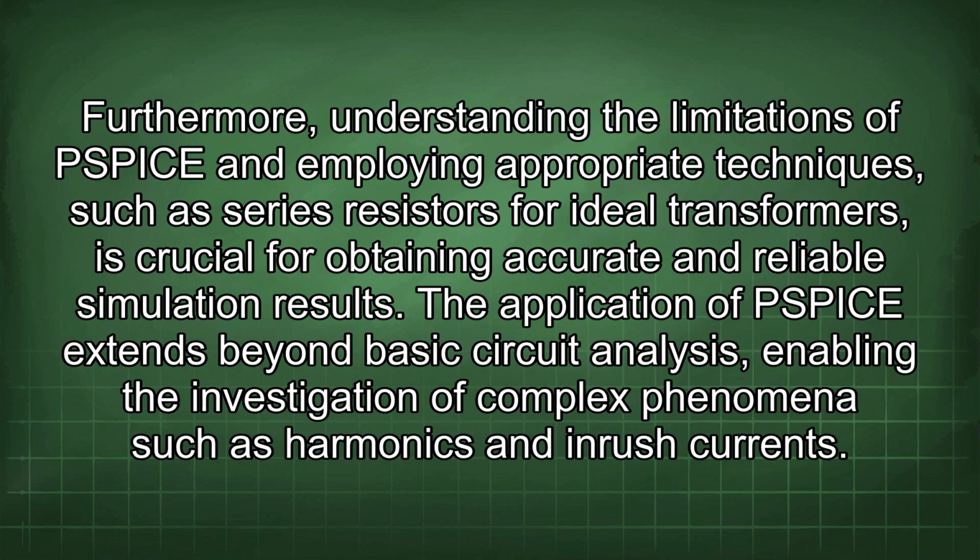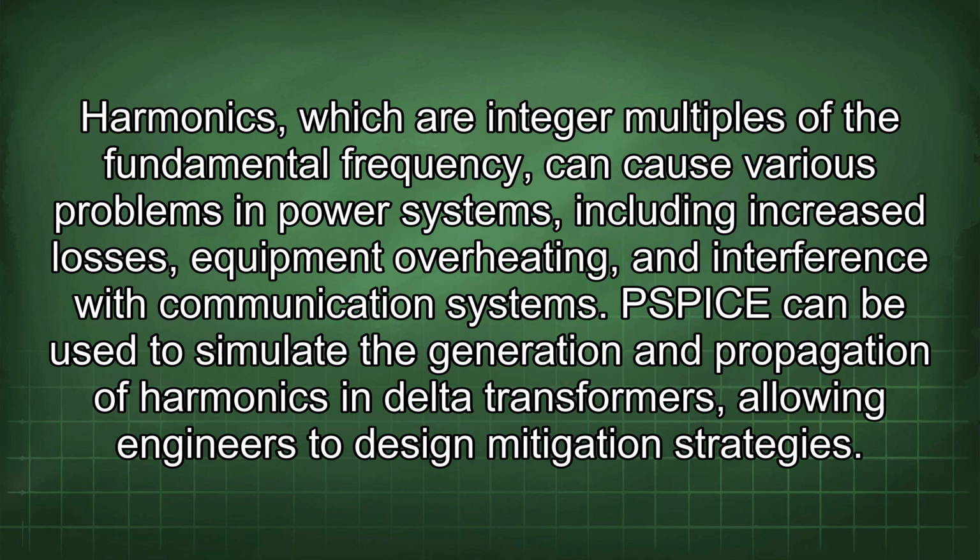Furthermore, understanding the limitations of PSPICE and employing appropriate techniques, such as series resistors for ideal transformers, is crucial for obtaining accurate and reliable simulation results. The application of PSPICE extends beyond basic circuit analysis, enabling the investigation of complex phenomena such as harmonics and inrush currents. Harmonics, which are integer multiples of the fundamental frequency, can cause various problems in power systems, including increased losses, equipment overheating, and interference with communication systems.